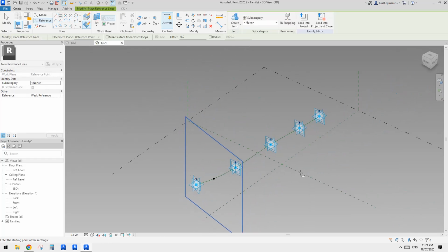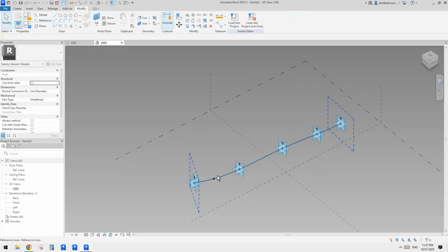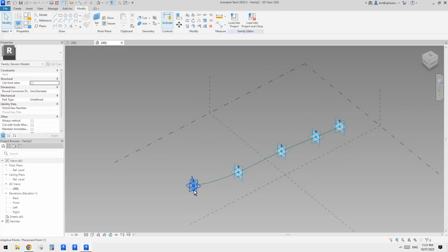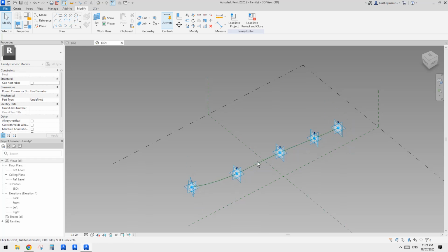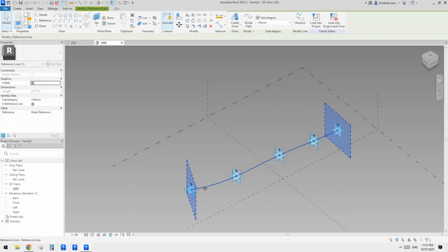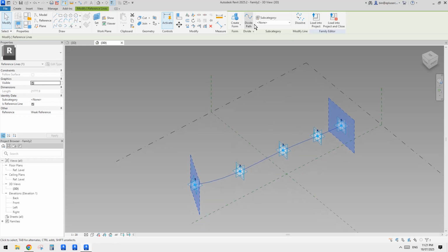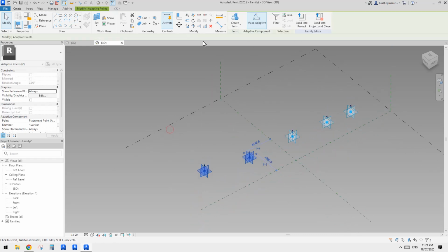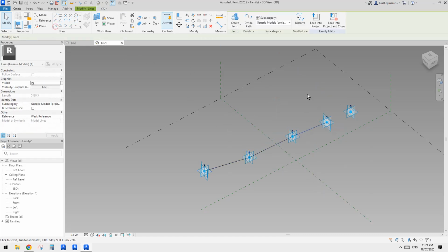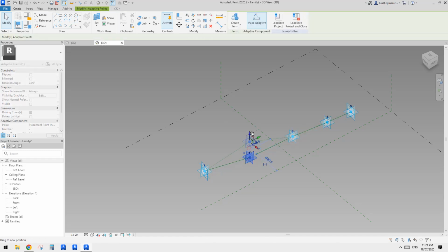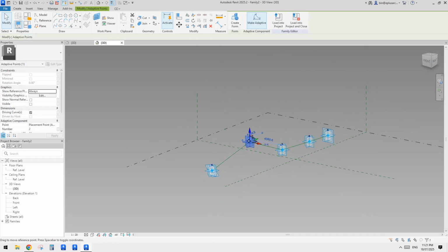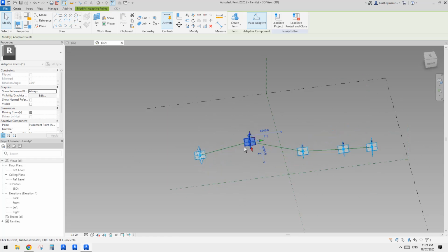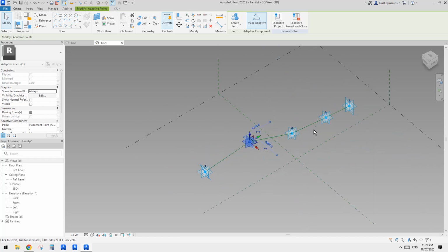Oh, hang on. No, wrong. Okay, so because we don't want a curved line, instead of selecting all of them and creating a spline through all these points, let me just dissolve it. We're going to create a spline between 2 points. Okay, so this means all these are straight lines, right? So which means if I move this point, you can see it will create all these straight line segments, instead of one curved spline.